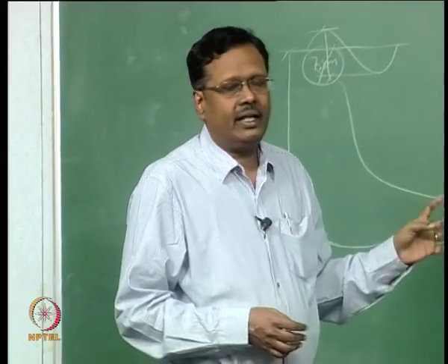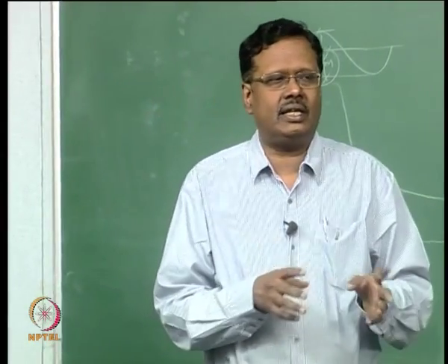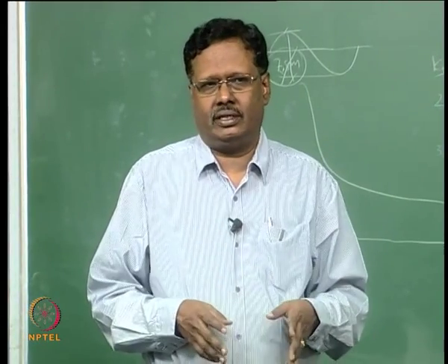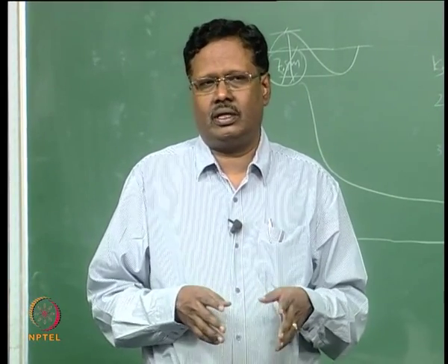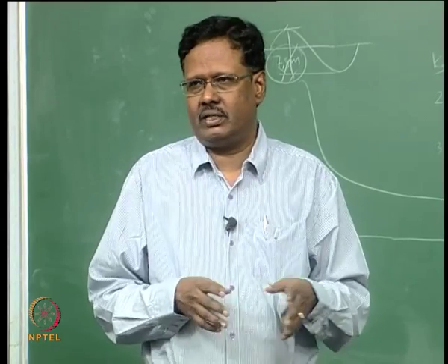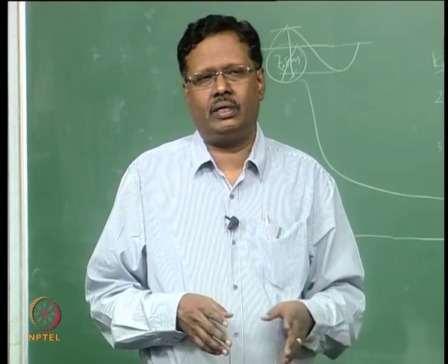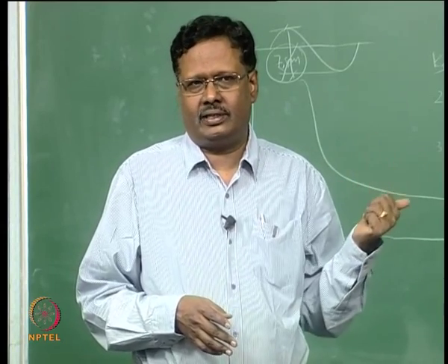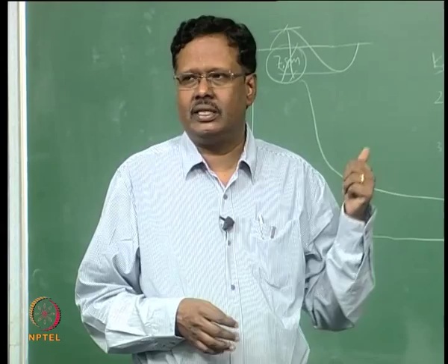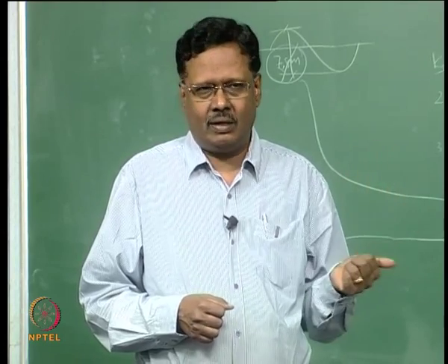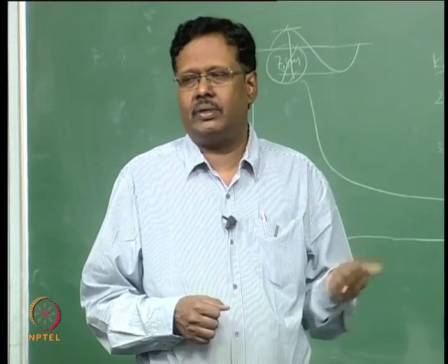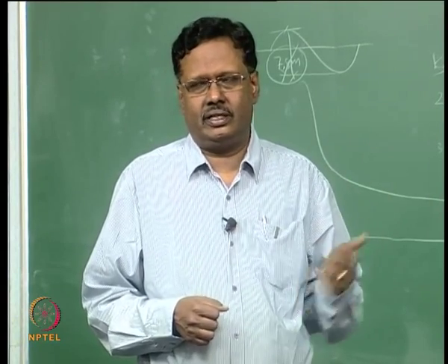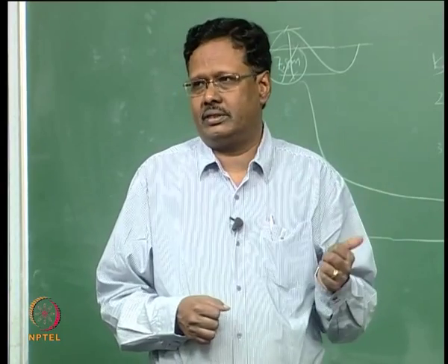So the 100-year is taken because twice the design life is considered as the life for which you have to design. There the fatigue comes into the picture. When you talk about the life of the structure, it is the fatigue design which controls. The fatigue design life will be twice the design life of the structure, that is why this 100-year comes into the picture. After 100 years the structure will not be safe, because there will have been so many storms and some damages. So you have to strengthen the structure after 100 years. That is the reason why we take 100 years.